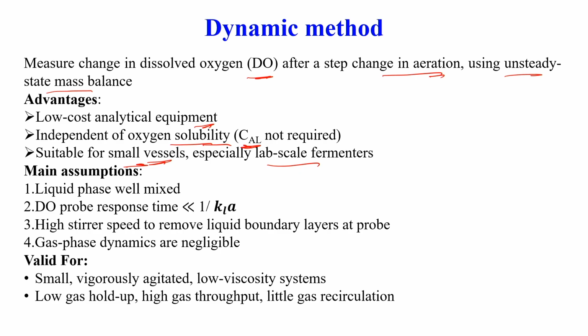Here again there are some assumptions: the liquid phase is well mixed, the DO probe response time is less than 1 upon KLa, and a high stirrer speed is used to remove the liquid boundary at the probe, because the probe is solid.